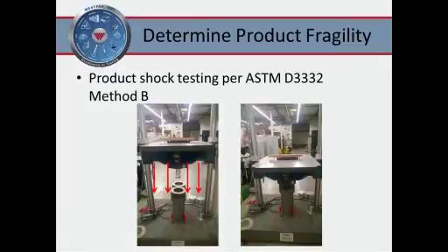For those of you that are not familiar with a shock tester or shock testing, here's just a picture from our lab of a shock tester. What the shock tester does is that you mount your unit rigidly on the table. So right here we have a laptop, and what happens is that you raise your shock tester and then it free falls onto programmers. And these programmers in this picture are nitrogen programmers, which will give you the trapezoidal waveform. But more importantly, they're programmable, which means that you could slowly step up your G levels until failure. So like I said, you start at a relatively low level, and eventually you stiffen up the programmers until you get the levels you want and the unit breaks. So this is just a picture for those of you not familiar with shock testing.